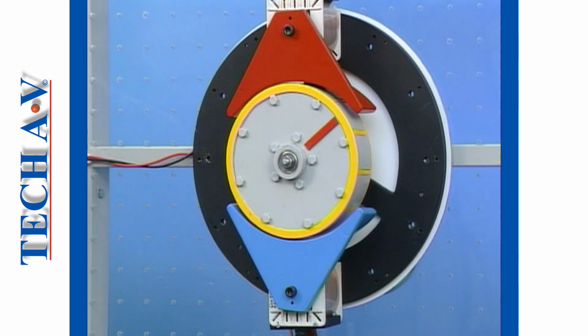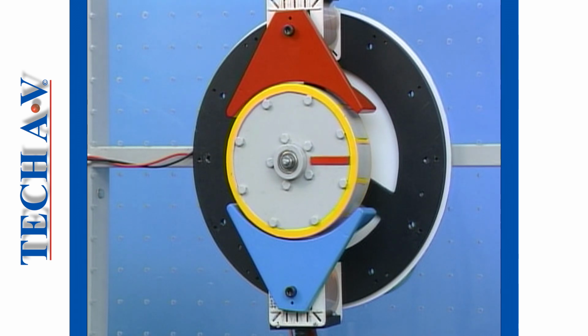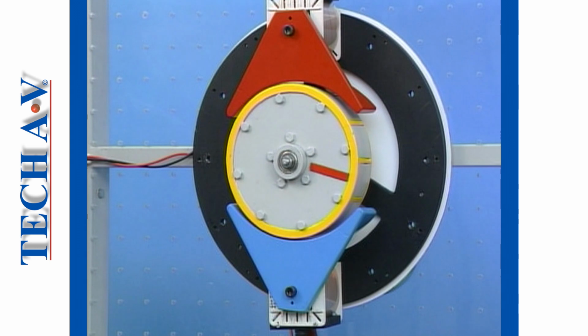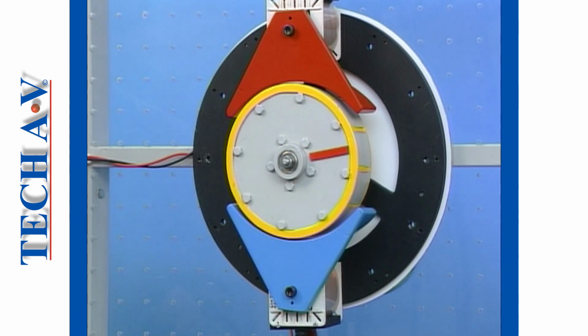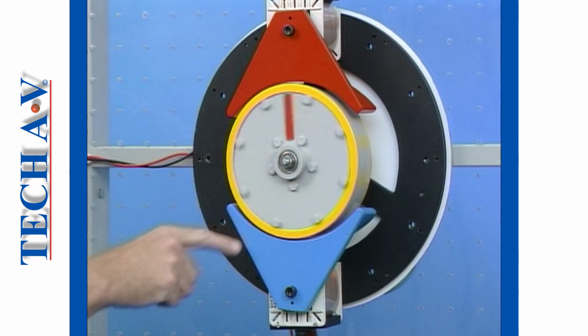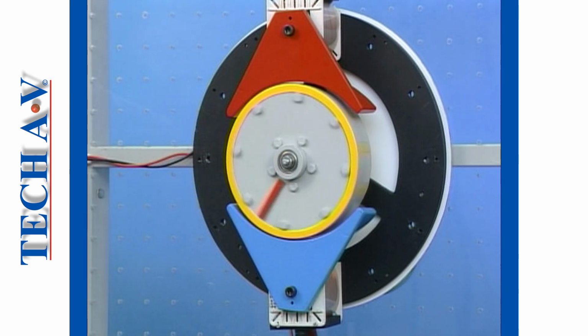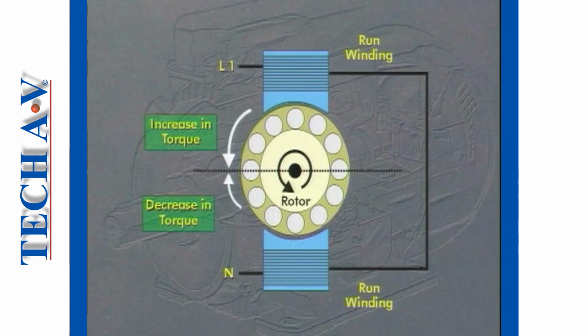Notice that the rotor is not self-starting, but oscillates backwards and forwards, since the pulsating magnetic field induces two equal and opposed torques in the rotor. In order to get the rotor to rotate, it is necessary to apply a force to the rotor at right angles to the main field. The applied force has in effect created an imbalance in the torques, and the resulting torque causes the rotor to turn in the direction in which it was started.